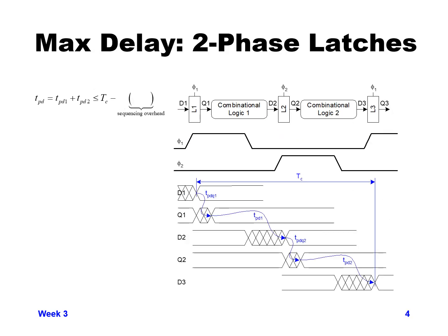Here we have a second example where we're using two-phase latches instead of flops. So in this case, to get one cycle through two-phase latches, we have 3 latches. Latch 1 and latch 3 are phase 1 latches, and then the latch in between is a phase 2 latch. Remember, we always have to have phase 1, phase 2, phase 1, phase 2 is the way that two-phase latch design is designed to work. So in this particular case, if we look at our requirements based on a couple slides ago, we have a certain cycle time.